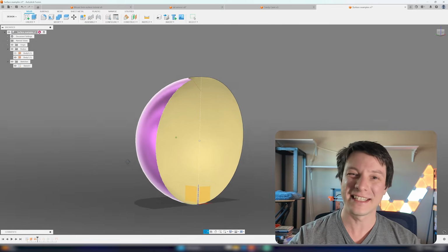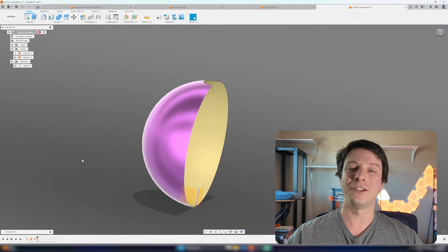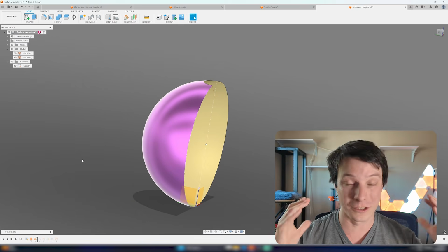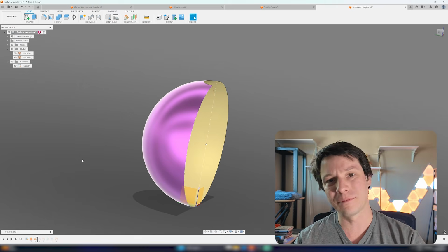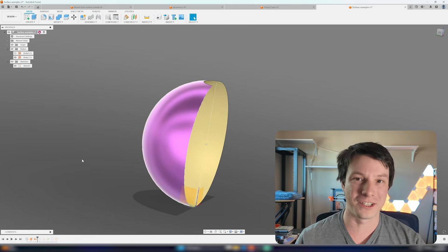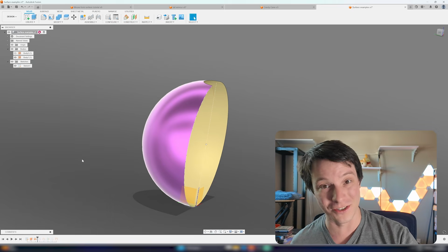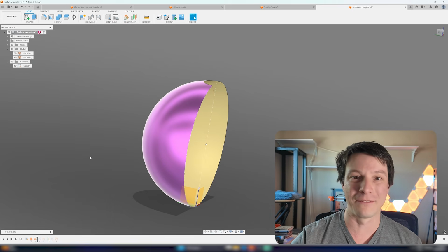But with surfaces, because there's zero thickness, you need to make sure that if you're using them, that you end up combining them in such a way that they form a manifold, completely sealed, watertight mesh, or use them as part of the modeling process to cut away a solid object or modify in such a way that you end up with these volumetric shapes that can be reproduced. And that's one of the fundamental pitfalls that people fall into with surface modeling when they first start.